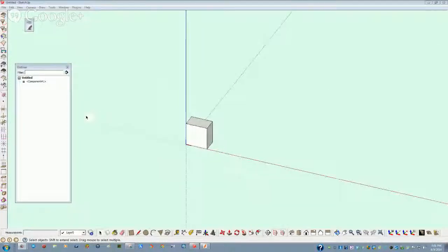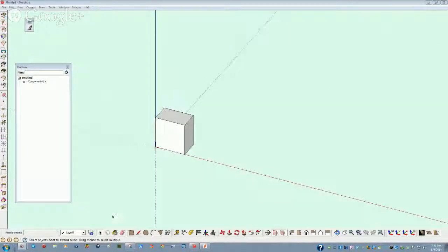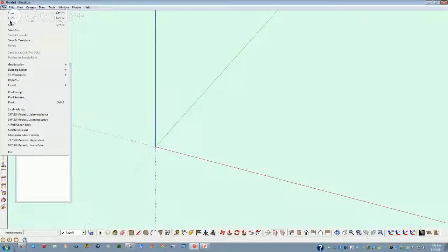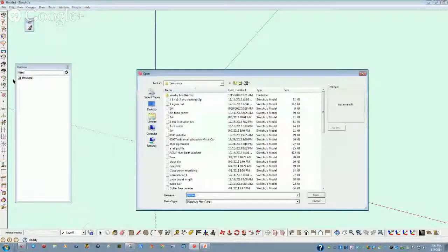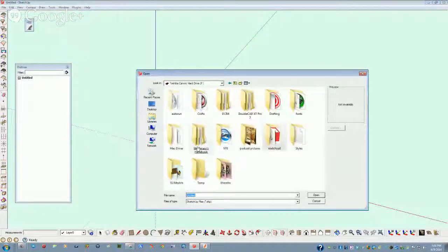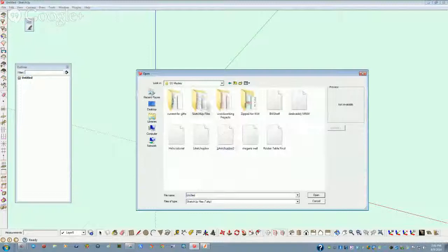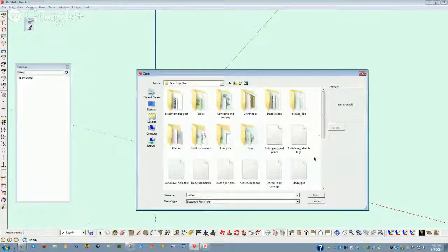And here's my SketchUp workbench. First thing I'm going to do is delete component 1. Now I'm going to try to go to import and import the JPEG. So import, mouse button 1 on file, scroll down, select import. It defaults to the last place you imported from. So we'll go up to SketchUp models, SketchUp files, and then it only wants to import SKPs.